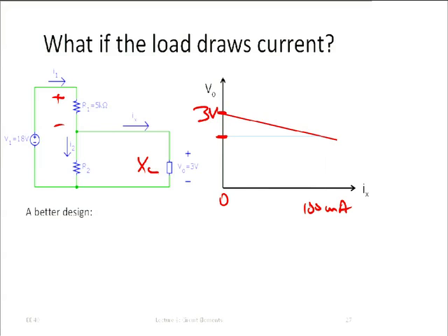Well, that really would be a totally impractical, useless circuit. So in practice, every circuit will accept a certain tolerance, and you need to look that up in the data sheet. So for our example, we assume that the component works for a voltage as low as 2.5 volts and as high as 3 volts. And the current is going to vary between 0 amps and 100 milliamps.